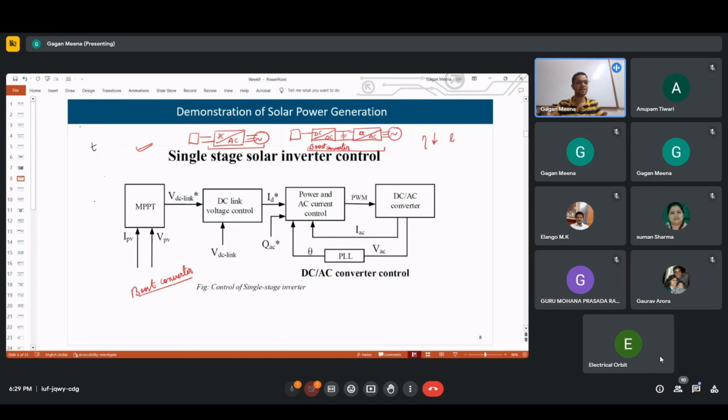And then there will be such small transformers. Again, several transformers will be in parallel. Suppose the rating of the plant is 5 MVA, 5 megawatt. So a 5 MVA transformer is being used at the top level. Below that 5 MVA, there can be five 1 MVA converters.